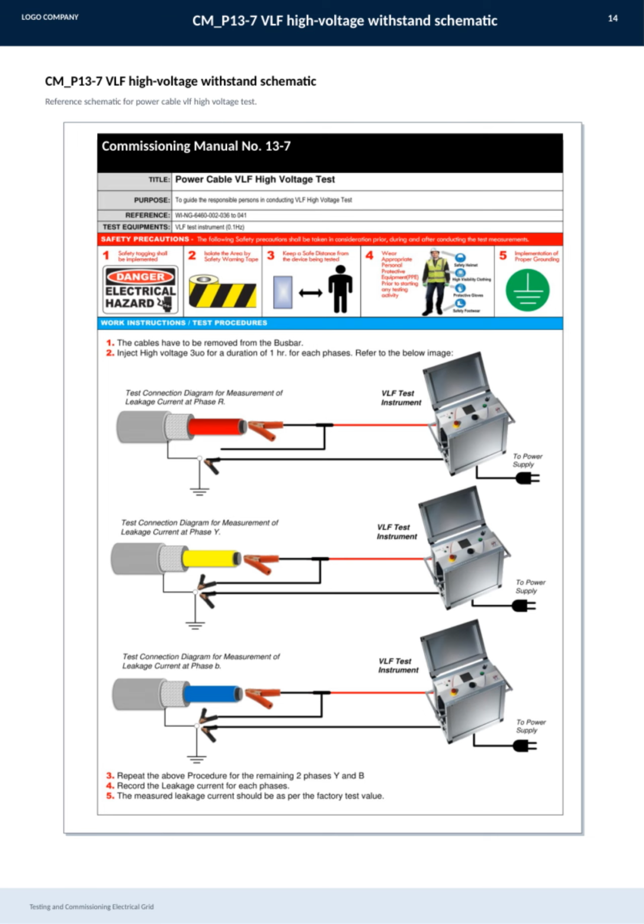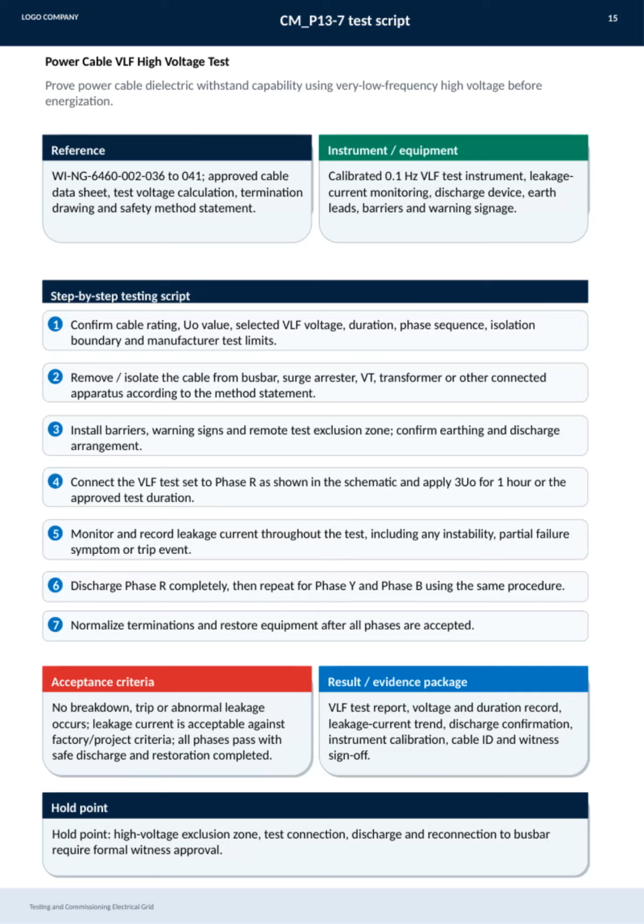VLF withstand test correctly. This slide outlines the power cable VLF high voltage test, a crucial step in testing and commissioning the electrical grid. The main goal here is to prove the cable's dielectric withstand capability using a very low frequency high voltage before energization. We follow specific references, including detailed work instructions, cable datasheets, and safety statements.